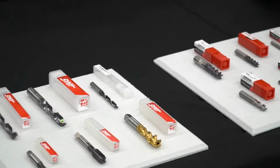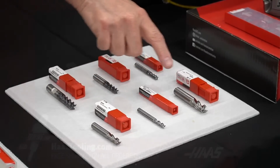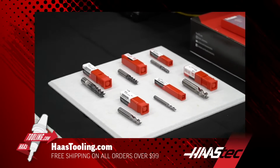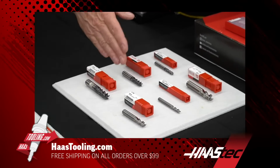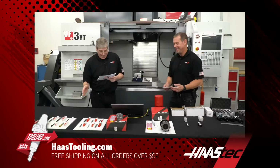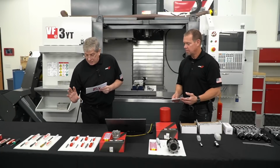End mills, solid. Here's a range of solid carbide end mills that we carry. First, we're going to start with the 3 fluters here. We've got a 1/4 inch, 3/8, and 1/2 inch version of this to show, but we carry these in 10 sizes. Again, primarily designed to rip aluminum. All of our 4 flute and 5 flute end mills are Talon coated, titanium aluminum nitride. We carry those in a range of 15 different sizes for the 4 fluters and 13 different sizes in the 5 fluters.